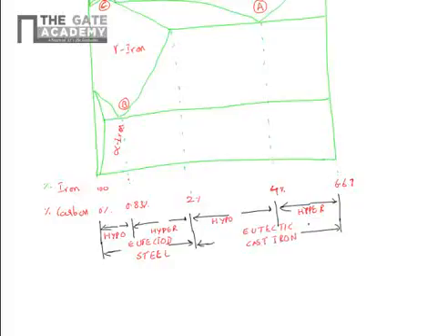So what it explains is, if any component has more than 2% carbon, then it is called cast iron. Steel means less than 2% carbon. If it is less than 0.83% carbon, it is called hypoeutectoid steels. If it is between 0.83 and 2, it is called hypereutectoid steels. Similarly, more than 2% carbon is cast iron. 2 to 4 means hypoeutectic cast iron, and above 4 is hypereutectic cast iron. So depending upon the percentage of carbon, the name of the component varies.